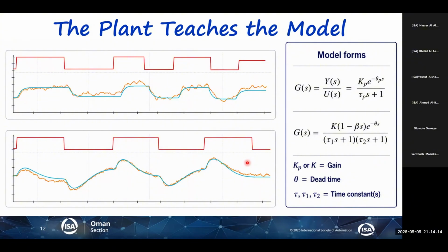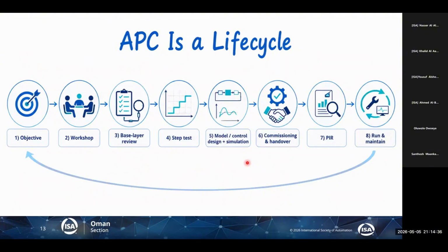And it's very important that you document this. So before the simulation, you write all the scenarios, have it reviewed, and all the expectations, what I expect as per the control and optimization objectives. And then you document what you have seen. This way your peers can also help you to review. And it takes time.